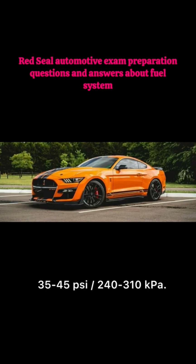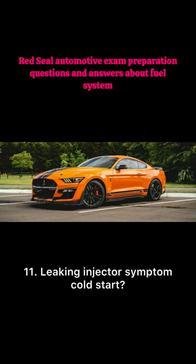9. Why test injector resistance unplugged? Avoid false readings and ECM damage. 10. Fuel pump driver module purpose. Controls pump speed on returnless systems. 11. Leaking injector symptom cold start. Hard start, black smoke, fuel smell.